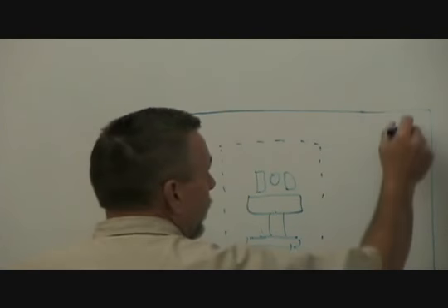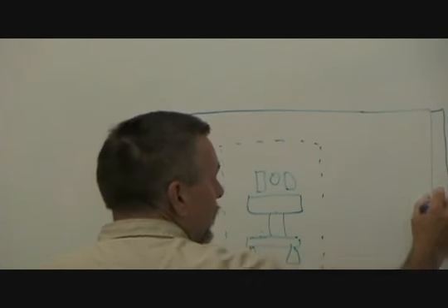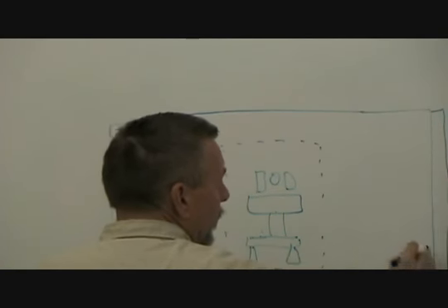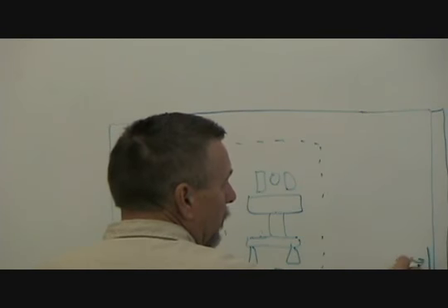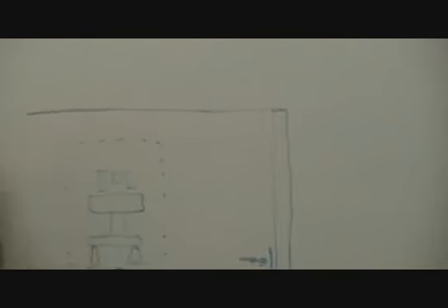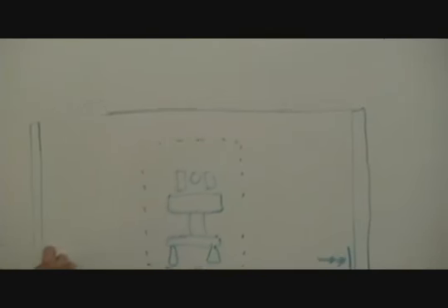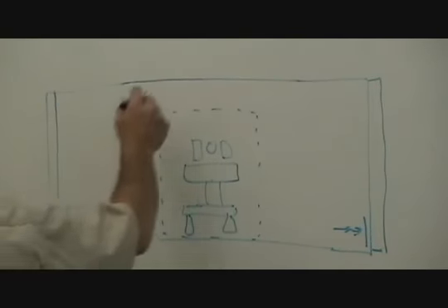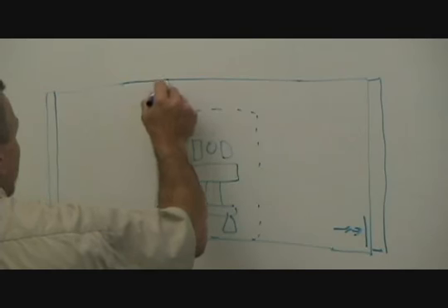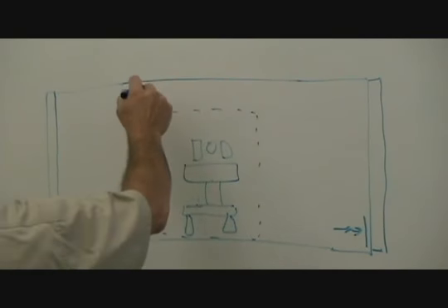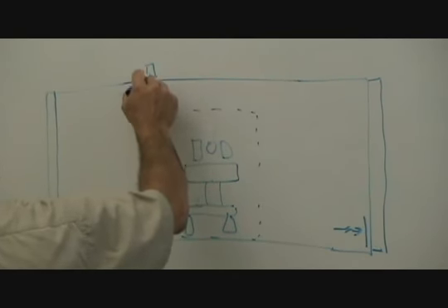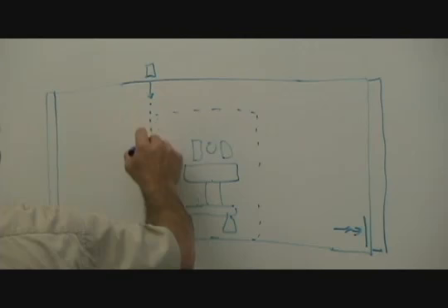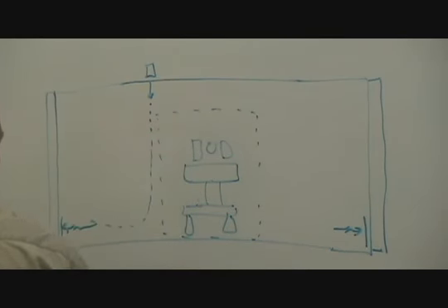So my return is in a chase. So I've got a low return right here. And in the other corner, another chase, a low return right there. The idea is to supply some type of air diffusion where there might be slots that you're discharging air straight down like this, and the air flows like that.